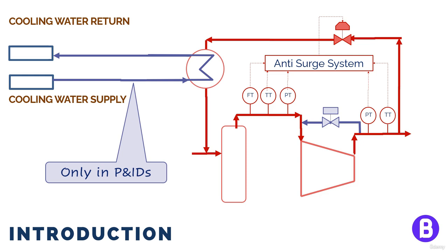Of course, the P&ID shows much more details. So in such a P&ID, we shall add isolation valves, fittings, instruments, PSVs, shutdown protection, and many other requirements as we have shown in the last videos. We shall go through each of them in detail in the next lectures, but here we are just showing that there are lines that are shown in the P&ID while not being shown on the PFDs.